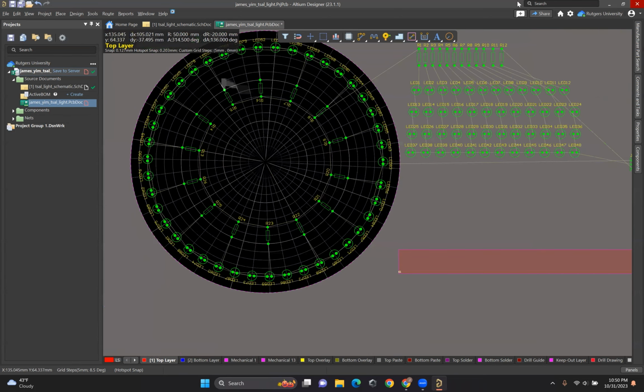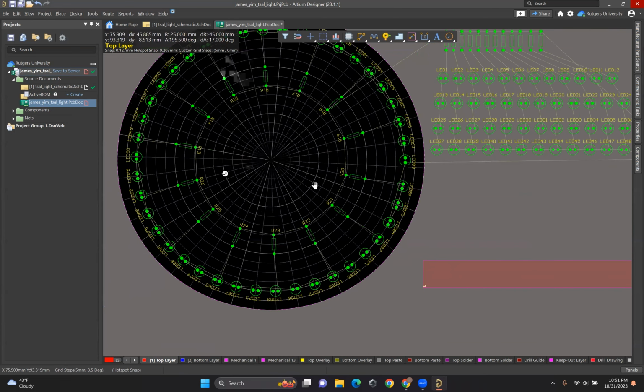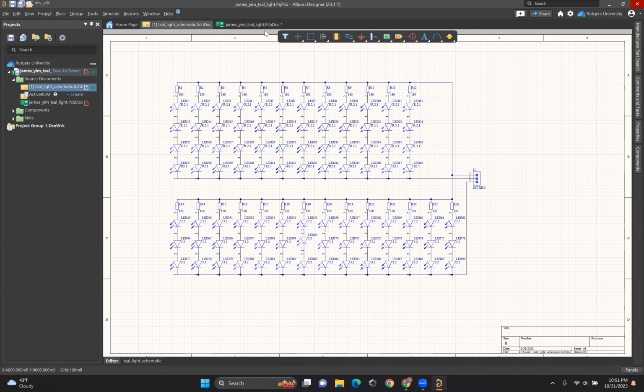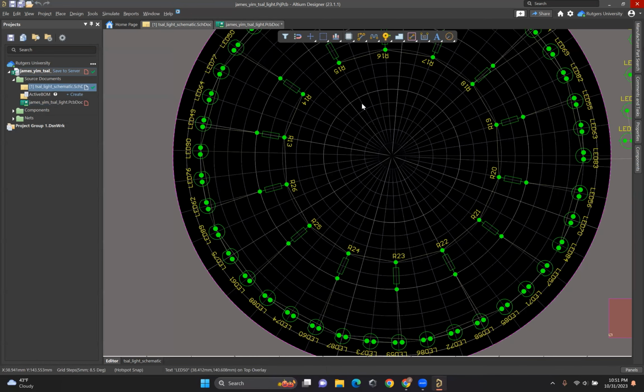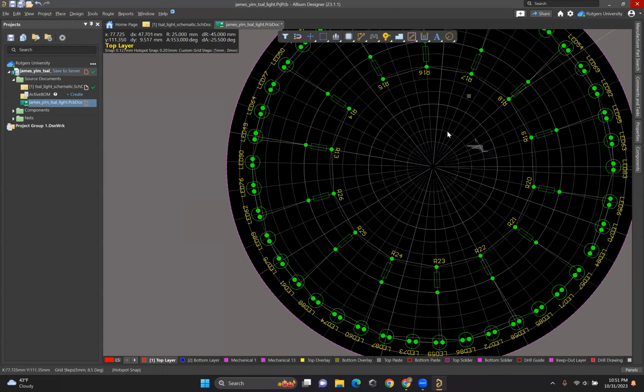All right, so now you can see I have all my resistors laid down, and then you have this little chain of three LEDs that follow each resistor, and then they connect to ground, which is not really ground. That's how we're triggering them, but they connect to pin 3 of the JST connector. And up here, these resistors are all permanently tied to 12 volts, which is pin 1 of the JST. So that's why I keep these nets going across. They're all connected to the same thing, so it's easier to have them like this.